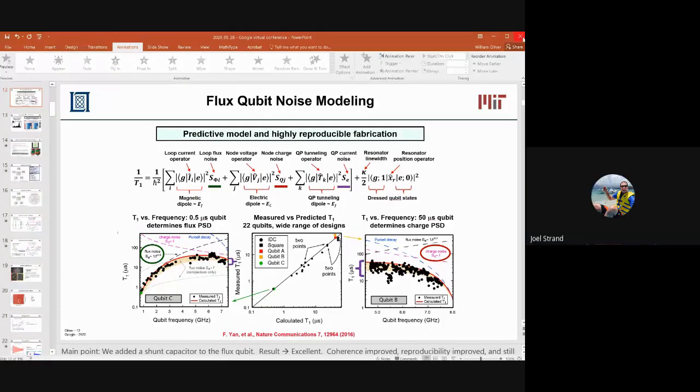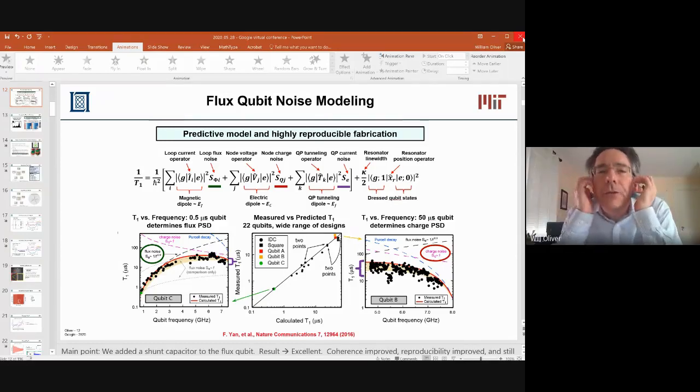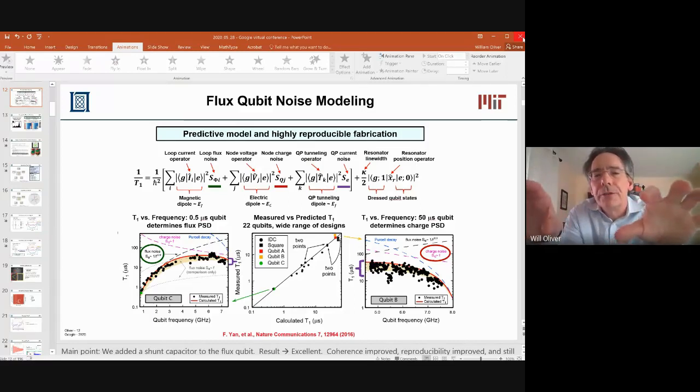I was just going to ask, you mentioned that for the CZ you could keep the qubits and the composite qubit at degeneracy. Are you just sweeping both flux biases on those two coupled qubits simultaneously, basically? Yeah, that's right. So anytime we want to change the qubit frequency of a composite qubit, we have to simultaneously apply flux biases to both underlying transmons. And that's 2 transmons per composite qubit. So if we do coupled composite qubits, we're actually simultaneously biasing 4 underlying transmons.